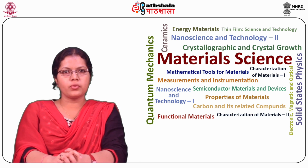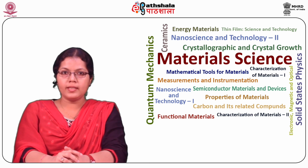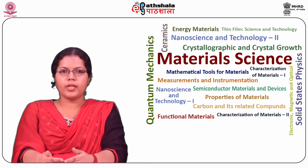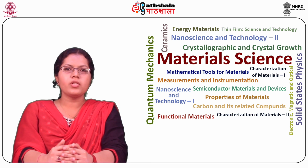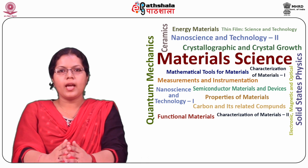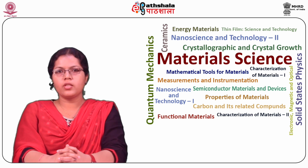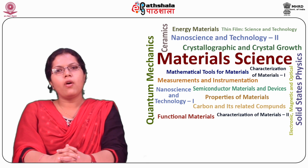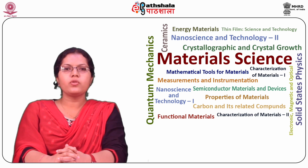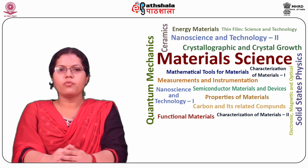First, the thermoelectric transducers. These are based on the property of thermoelectricity generation. Devices such as thermocouple, thermopile, and thermocouple gauge are based on this property for their application in the measurement of temperature, radiation pyrometry or temperature of distant objects, and low pressure respectively. Second is piezoelectric transducers. These are based on the property of piezoelectricity generation. Devices such as piezoelectric transducers are based on this property for their application in the measurement of pressure.